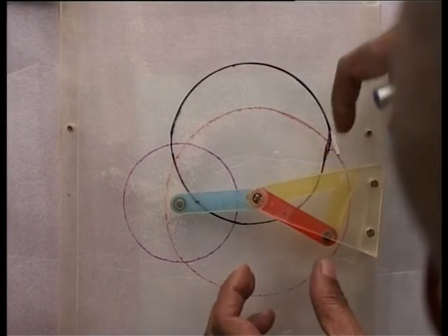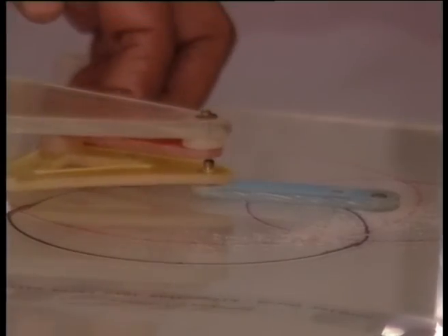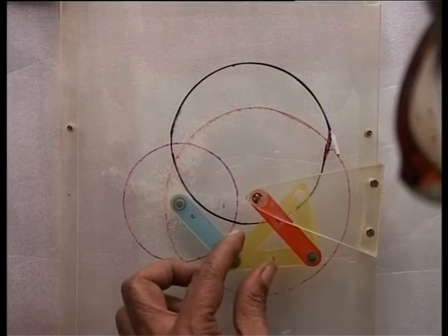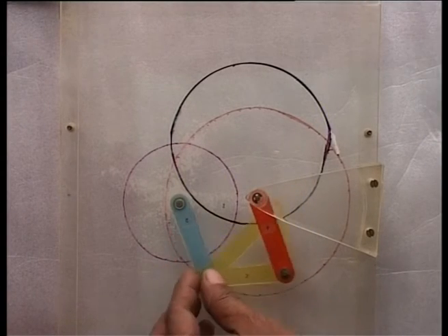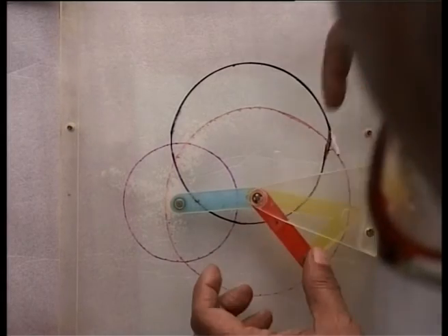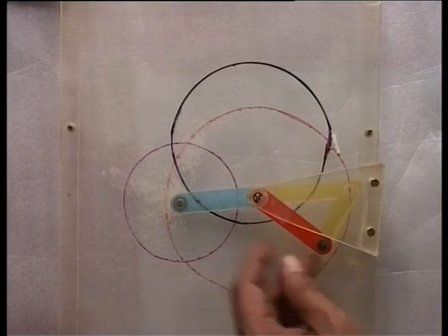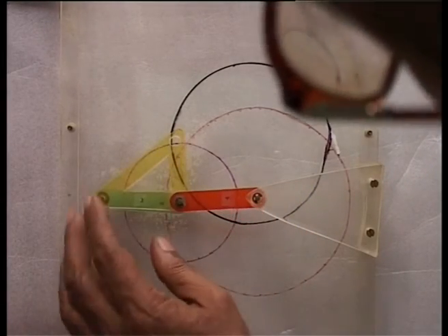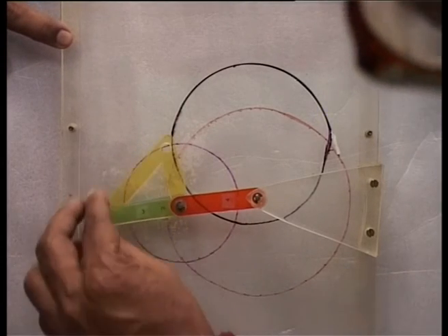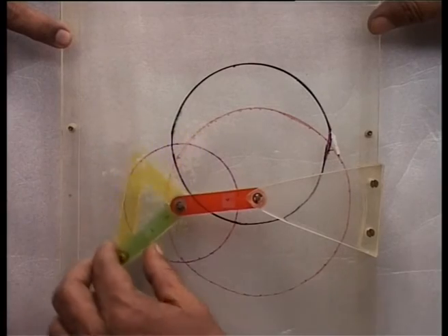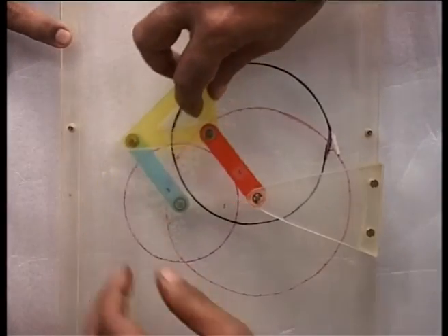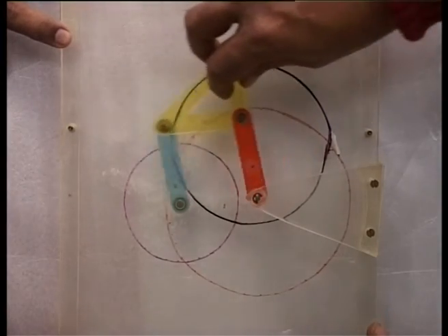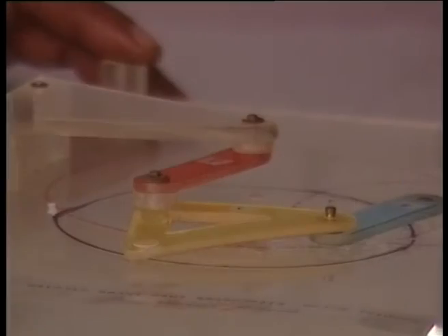However, in this rhombus linkage also, as we see, there are uncertainty configurations where all the 4 revolute pairs become collinear, and at these uncertainty configurations the linkage moves in a non-unique fashion. If we maintain the rhombus, it moves with a positive transmission from input to the output, whereas at this uncertainty configuration that linkage moves in an altogether different way. There is no transmission from this link 2 to link 4. Again here we get into uncertainty configuration, and there is no transmission from the input to the output link. However, one can maintain the rhombus and get positive transmission. So, this behavior is very similar to a parallelogram linkage.